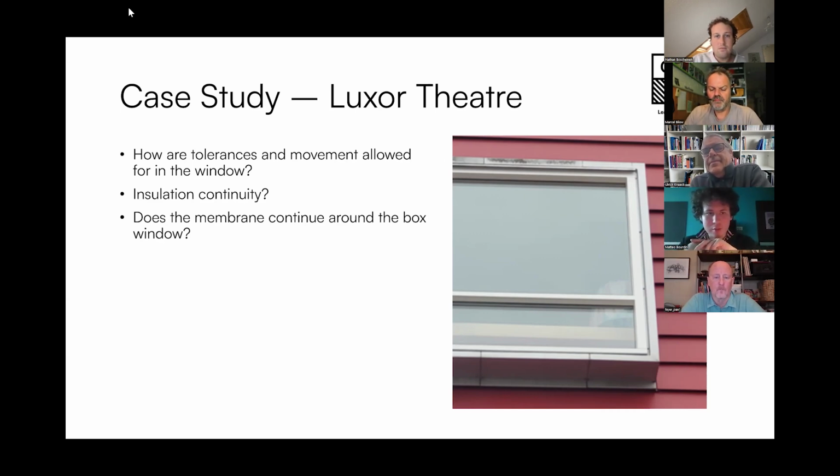That's why I took this project, to test out details from this. So the main question is how do we deal with tolerance and insulation continuity, plus also water tightness, when you have a huge steel profile that goes out of the facade and has 15 centimeters from the window insulation to the actual insulation, and how you deal with this gap.